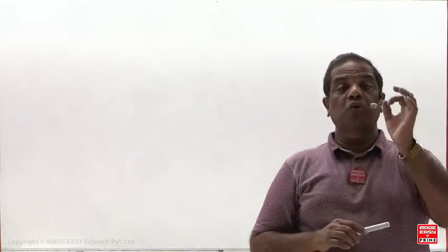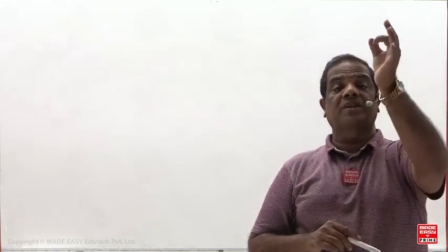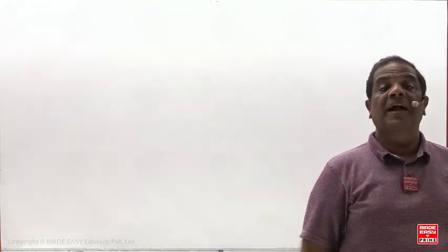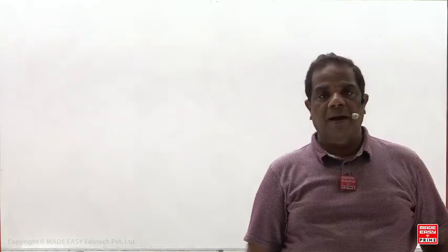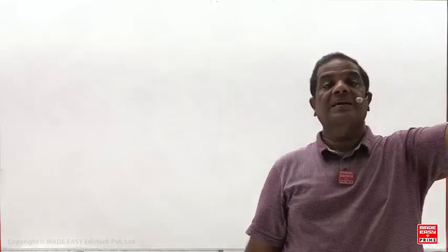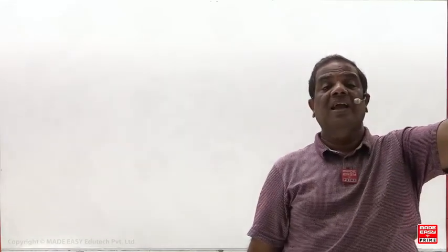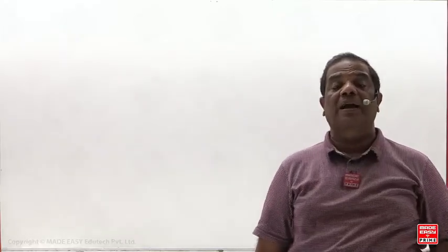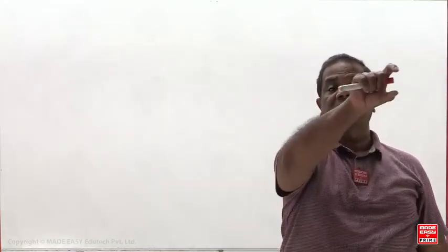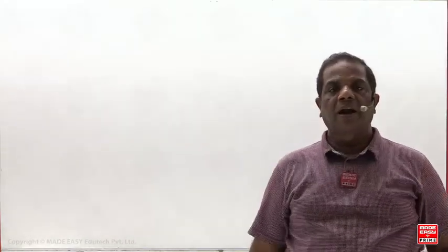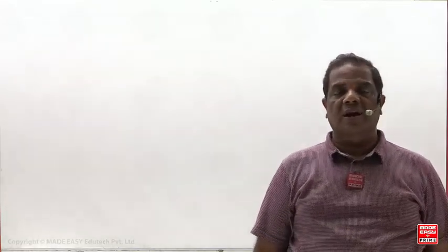So when two equal and opposite twisting couples are applied at the extreme ends of the member, it is pure torsion. It means the torque diagram is a rectangle, meaning at every cross section you are going to get an equal and same magnitude of twisting moment. Then the torque diagram is a rectangle, and automatically the remaining three loads are 0. What are the three loads on the cross section now?